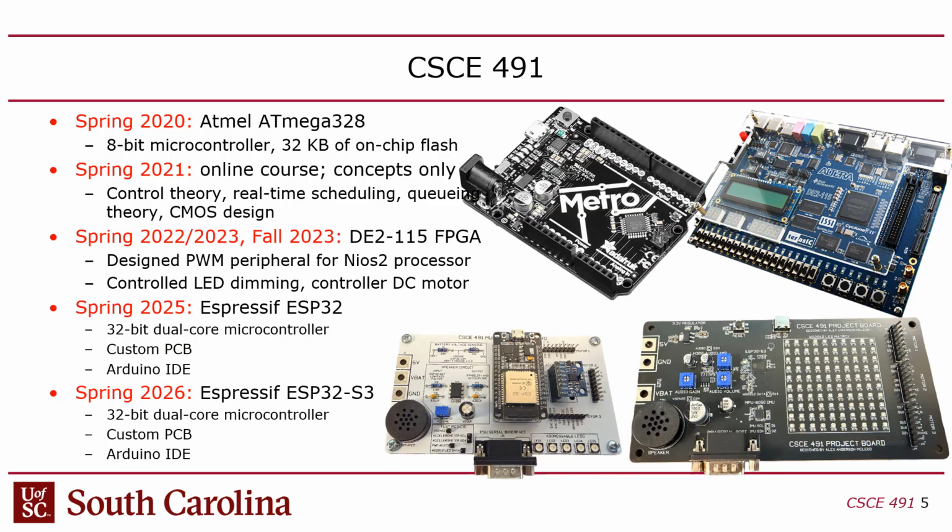The other thing I really liked about this board was we put these individually addressable LEDs. They used to call them NeoPixels, but I guess they're just kind of generic now. These LEDs have 24-bit color, right? Which is 16 million colors. So each of these LEDs can light up in 16 million unique colors. And the really cool thing is that they're connected in series, so they're scalable, right? You can connect as many of them as you want.